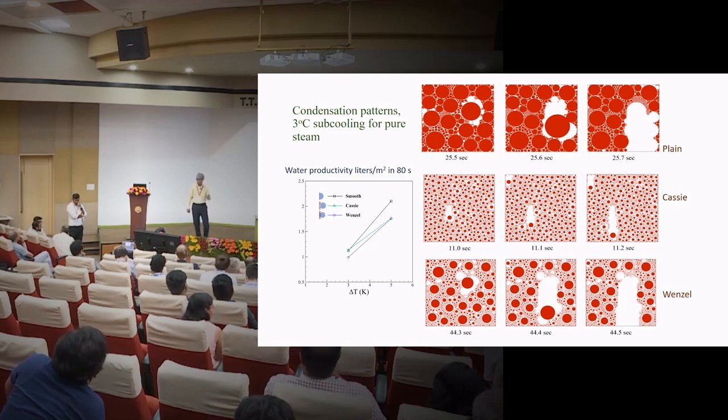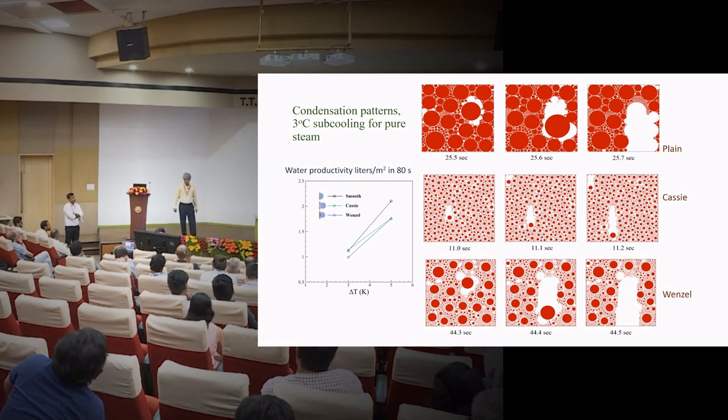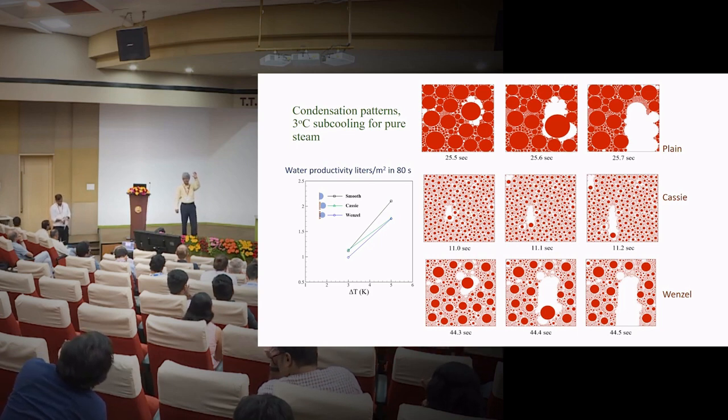Whether it is drop-level interactions or at the scale of condensation, there are some macroscopic continuum-level quantities that you have to prescribe, like equilibrium contact angle, pinning coefficient or hysteresis, advancing and receding angles. And then there is a friction coefficient at the three-phase contact line.